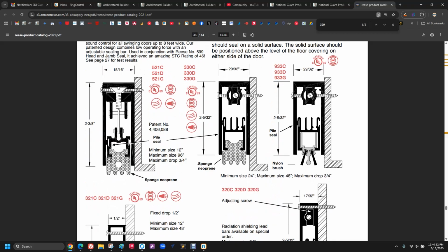It only drops when the door is pushed closed, and that's really effective because if you have an in-swinging hollow metal door or an out-swinging, and you have some sort of obstacle that the door has to swing over, if you had a traditional door sweep installed, it would drag across. Imagine the front door of a house. It's not hollow metal, although it can be, and you got a rug on the inside of that. The door glides over it, but your door sweep doesn't. Automatic door bottoms are perfect for that application.